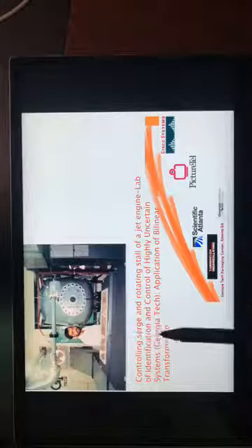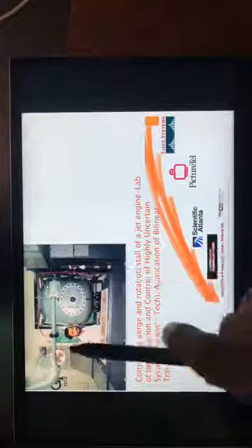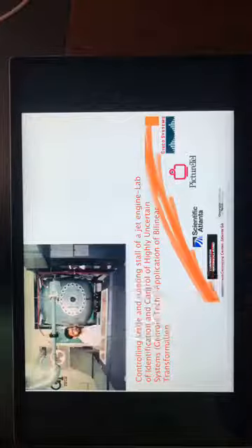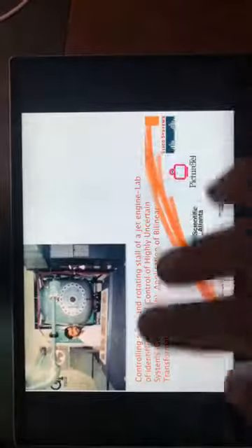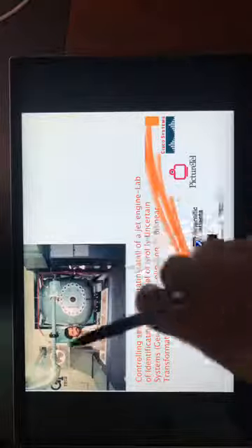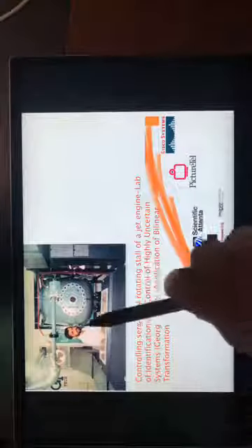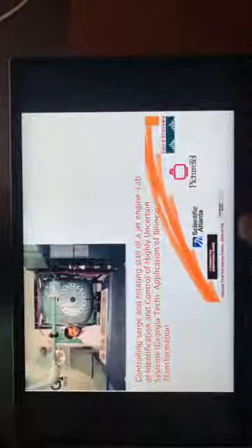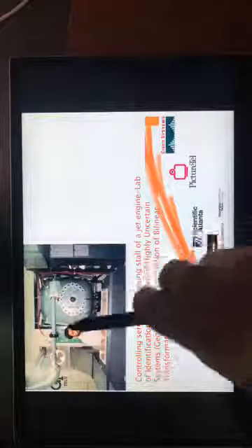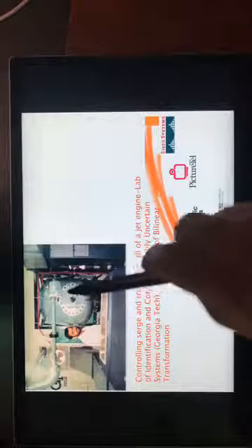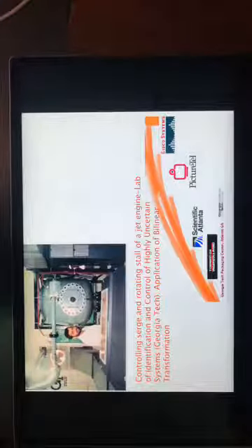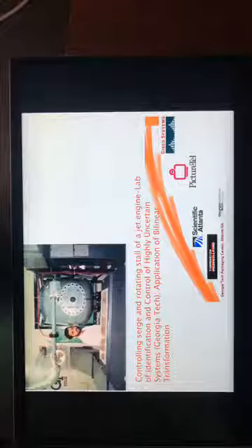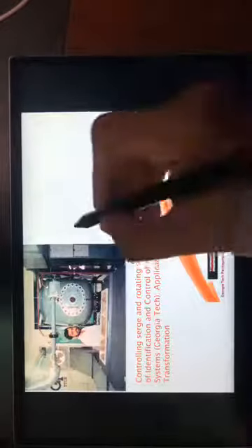And how was it done? They had several bleeding valves in this engine, and they would change the pressures. If their sensors, like pressure sensors, figured out that the engine or the compressor was getting into stall, they would bleed some of the air from different parts of the compressor and bring the engine back to operational, into working. So I was hired on this project,